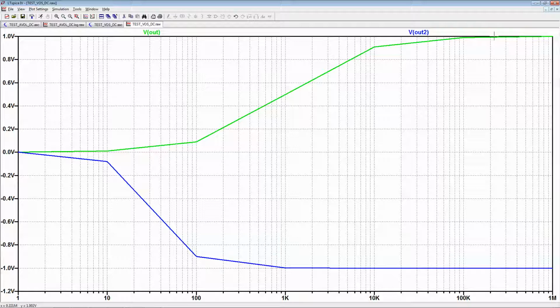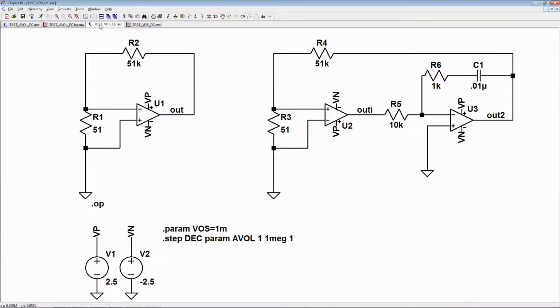I've been playing with it, I've been getting 50k. But notice in the enhanced circuit that even an open loop gain of 1,000 is giving us the proper gain. So given that we've been between 20 and 50k, this is going to be the circuit we need to use